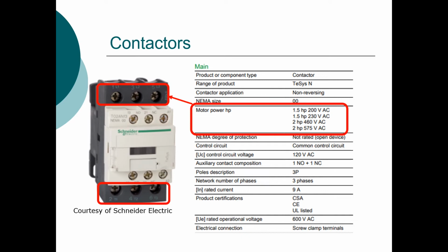If you remember when we looked at our schematic diagrams, we are able to separate my schematics into control circuit and power circuit. These contacts would be found in the power circuit and are called the power contacts inside the contactor. The other voltage value I should be able to recognize is my control circuit voltage, and this is also the voltage of my coil.